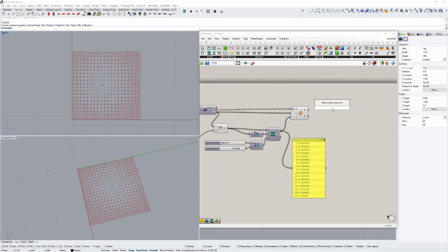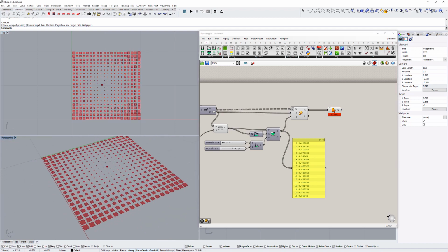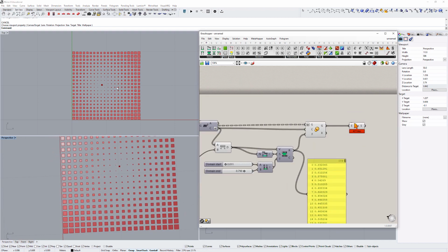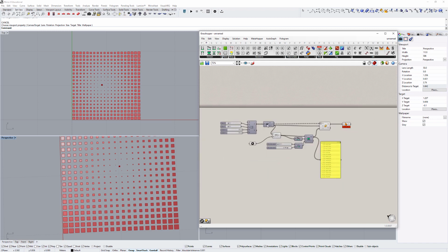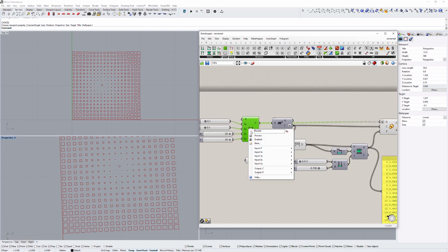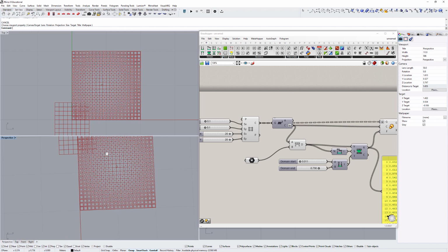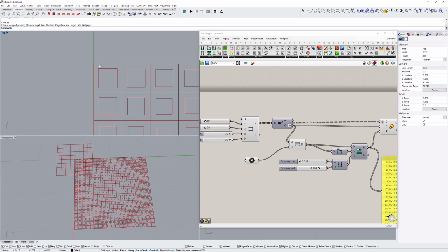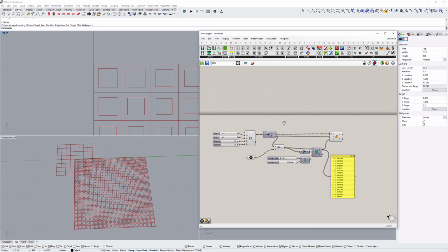So if you double click and type in boundary surface and put your G output for scale geometry into the input, we now have surfaces, and that red is just showing how long the process time took to compute. Something else that could be interesting is to turn this back on, our initial grid. And now we can look at that as a potential facade where you have a frame as the exterior panel and then glazing on the interior.